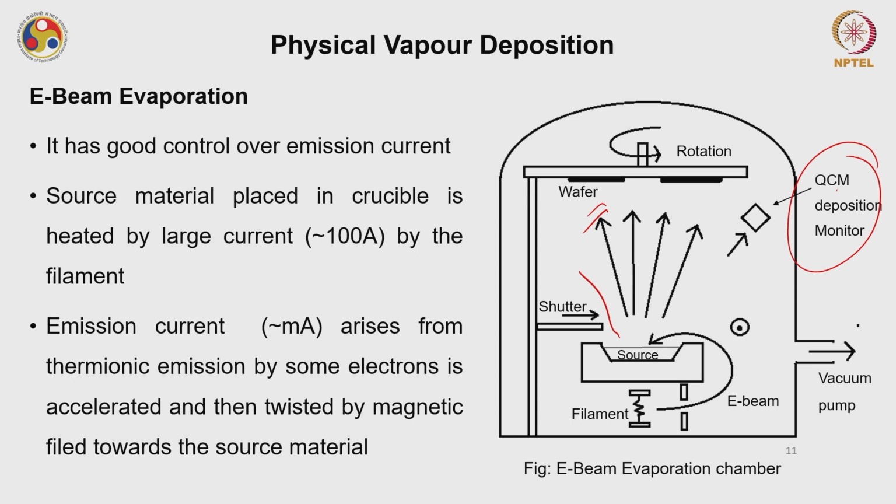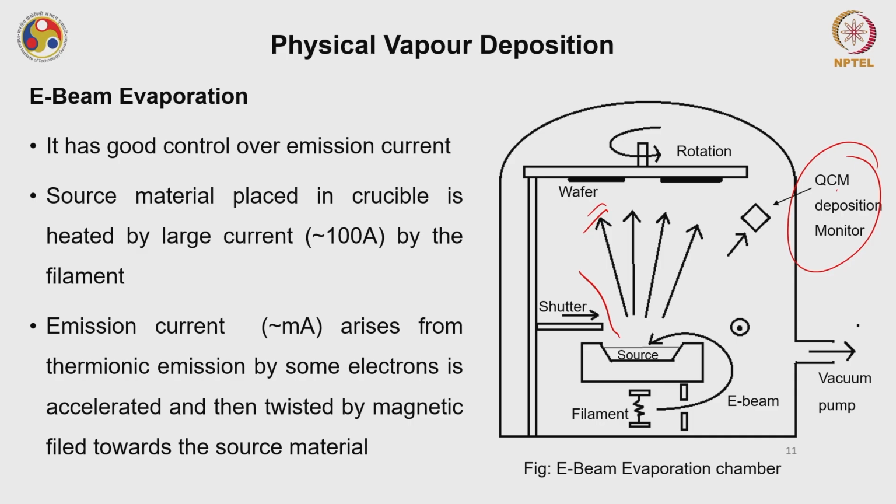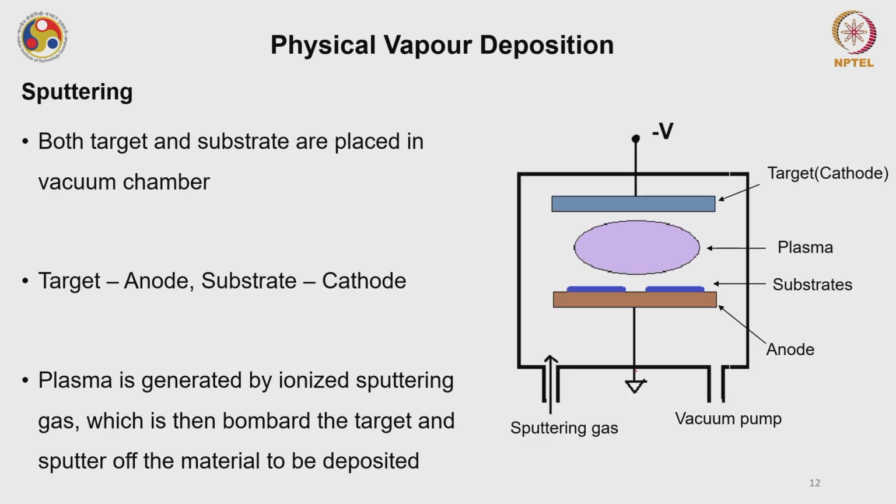You can achieve a certain level of uniformity in this e-beam evaporation system over the thermal evaporation system that you have just seen. However, the most advanced deposition systems are based on sputtering. Sputtering is used where your substrate or your target material should not see very high temperature. It should not be heated to that particular temperature, and mostly this process is CMOS compatible.